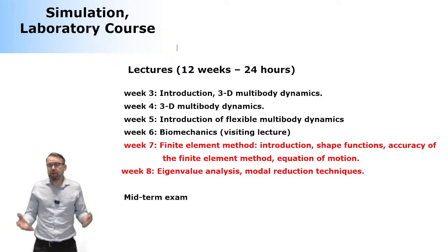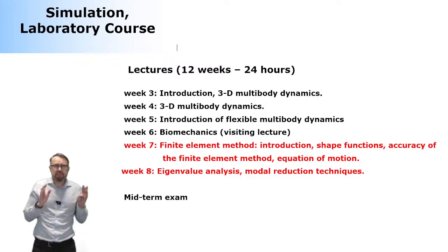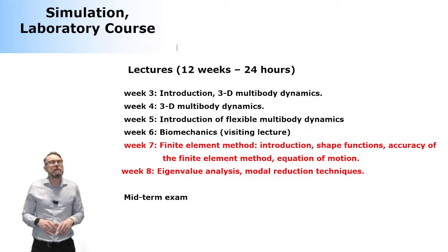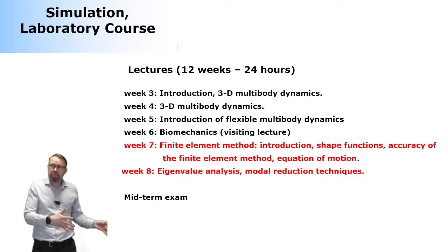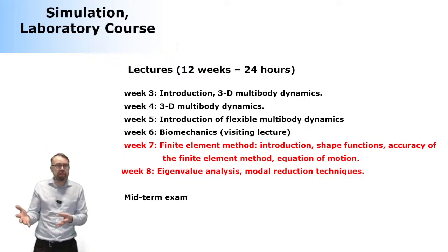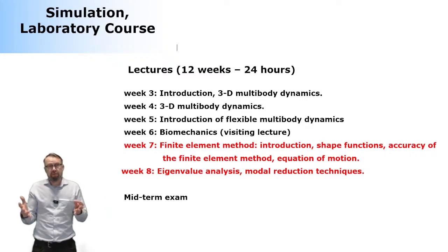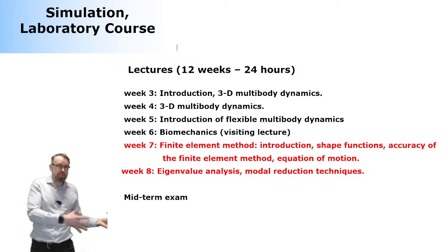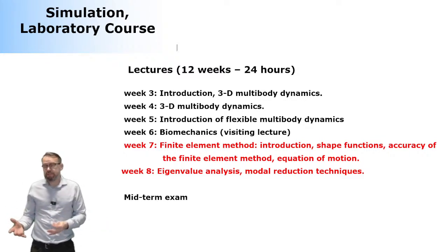You can also use an incremental approach, but as a general conventional finite element method is meant for something where the deformation is small and rotation with respect to the reference frame is small as well, which is okay if we combine this with multi-body system dynamics, because the large rotation will be handled by the reference frame, where the description is based on multi-body system dynamics.